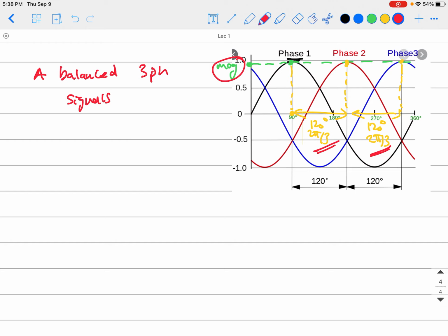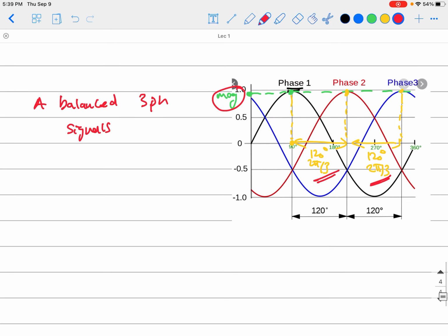So everything in the system will be in 3-phase, and that's actually what's happening in our public grid. The power generation happens in 3-phase. That means our synchronous generators, the machines that actually generate electricity, are built in 3-phase, and we'll talk about this in much more detail when we talk about synchronous machines. They generate 3-phase voltages like what you see in the photo here, and it's transmitted in 3-phase and goes to loads, which are also connected in 3-phase most of the time. Yes, they can be single phase, like homes, but again, they are connected in different phases to keep it balanced like 3-phase.